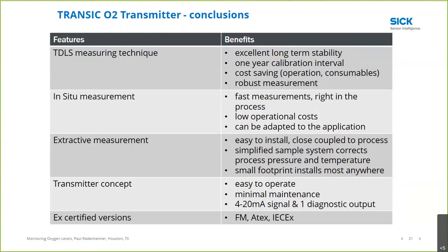In situ installations, you can accomplish both a zero and a calibration through flooding the sample cell through a calibration port. On the bottom of the analyzer, there is a gas port. You can hook that up. If you have the Teflon membrane in place, that offers you the opportunity to flood just the sample cell, and it will permeate out of the sample cell eventually and be swept away into the process or to a low pressure waste drain.